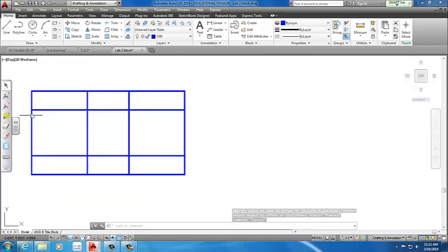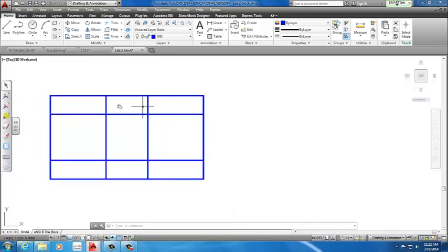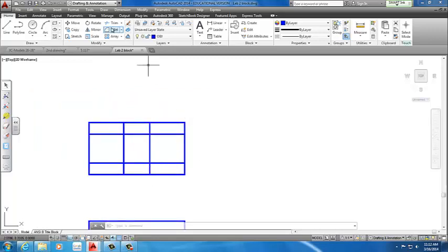That's the right quadrant. Since this line is completely full length, we're going to start with the left one. It will go directly straight down, making sure ortho was on. So we will need to trim these two parts, here and the bottom as parts. Doesn't matter what distance, as long as it's past the circle. To do that, we use our second trim command.